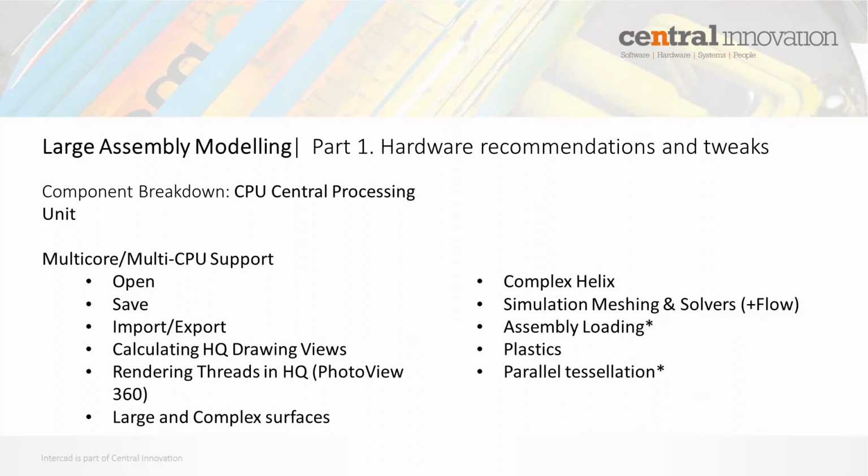Continuing on with the CPUs, SolidWorks does have multi-core or multi-CPU support. There are some low-level operations in the SolidWorks algorithms which use multi-threading, so Boolean, silhouettes, line generations, mass properties and body checking are all handled at the low level by SolidWorks modeling algorithms. These operations become multi-threaded in SolidWorks operations like the cut, extrude or emboss.